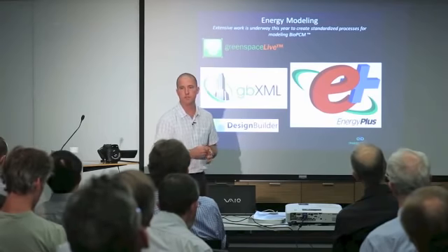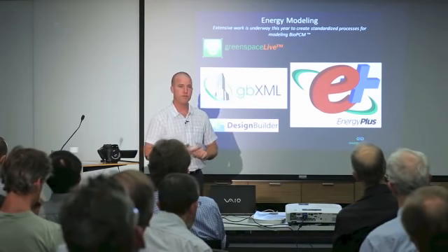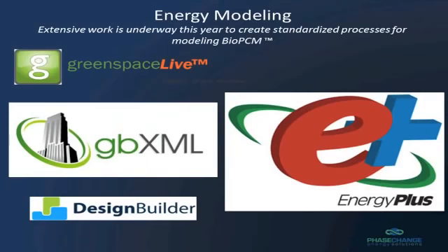Energy modelling, for those who use AccuRate, BERS and FirstRate, there's another program called DesignBuilder, which you might have heard of, which has actually got phase change material listed inside it now. So you can look up each material and work out how many kilowatt hours it will change the building by. You can model the house or the office without phase change material, then tick yes, insert the phase change material and see the difference based on the climate zone and all the other attributes of the building, to see how much energy you won't have to use.